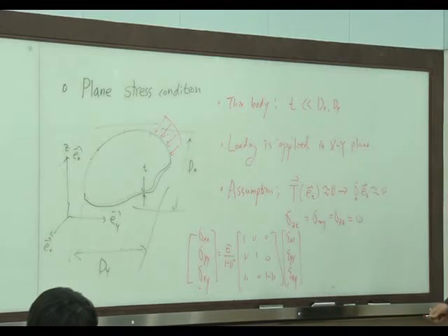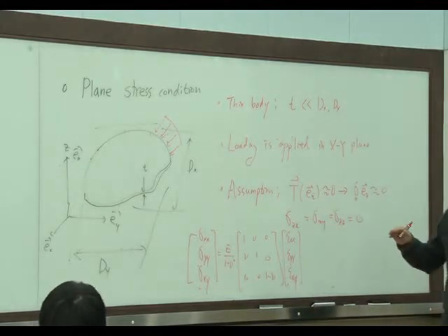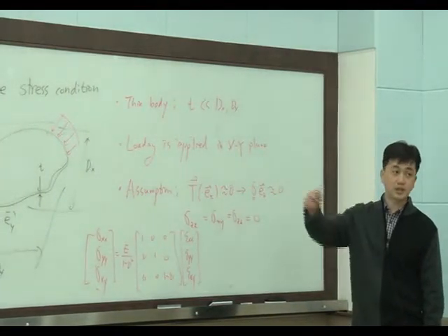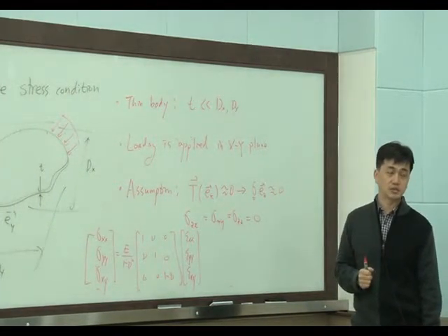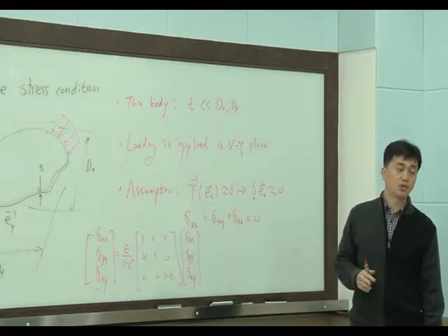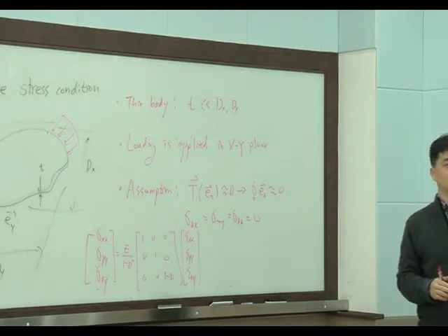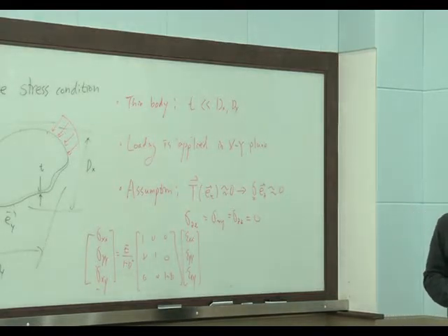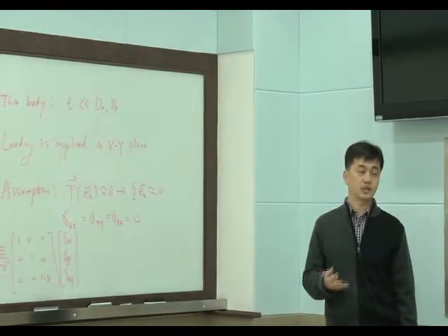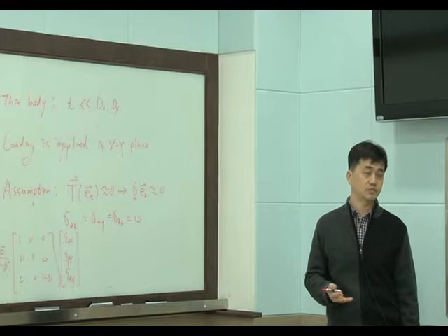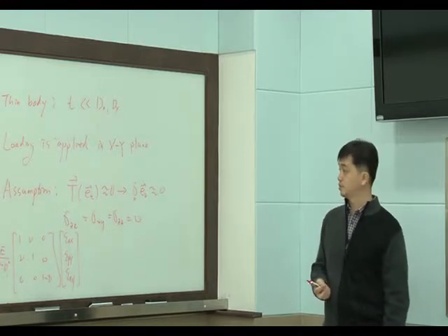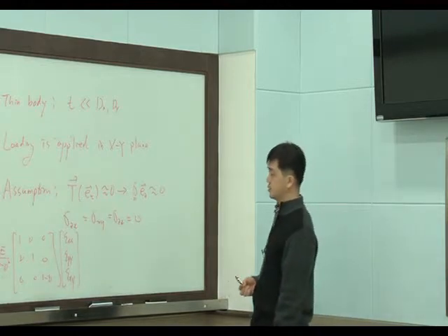We can use this simpler material law instead of the complicated 3D material law under the assumption of plane stress. So this can be used for thin bodies. Plates, shells and beams are usually very thin.